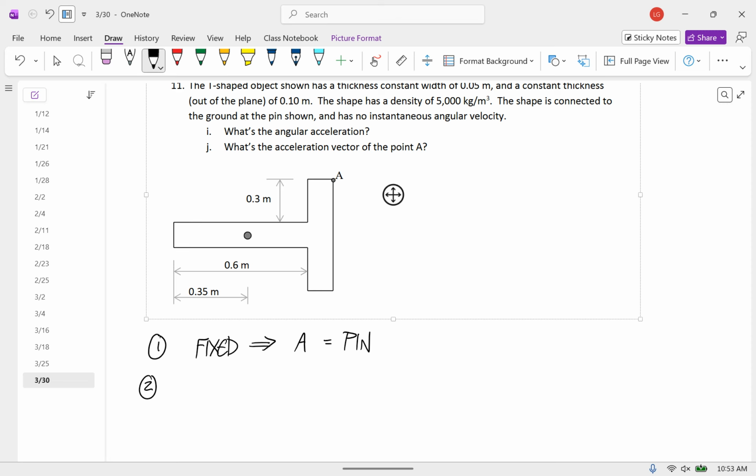So when you say fixed, it doesn't really mean fixed like to a wall. Right, not like a fixed joint, just a point that doesn't go anywhere. And so you're just looking for hinges, pins. Yeah, that's really all, I think. A friction contact would be another example.